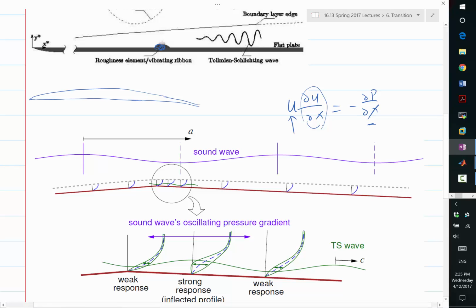So basically, receptivity is going to increase or decrease your critical N factor. If you don't have these receptivity sites, it can increase your N. If you do have these, it'll decrease your N.